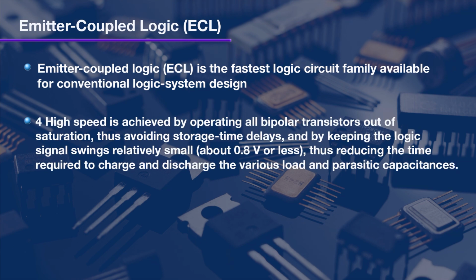High speed is achieved by operating all bipolar transistors out of saturation, thus avoiding storage time delay, and by keeping the logic signal swings relatively small.